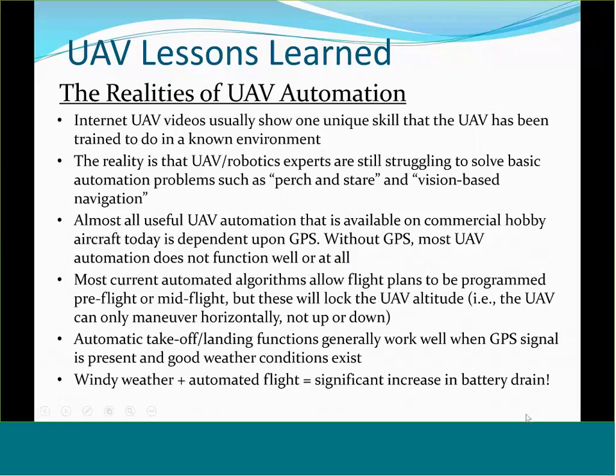If you don't have GPS signal, then you better have a backup plan because your platform is probably going to crash itself. In terms of windy weather and automated flight, if you have wind and you have pre-programmed flight paths, expect a significant increase in your battery drain. Your flight times may be diminished 30, 40, even 50% because of that wind.